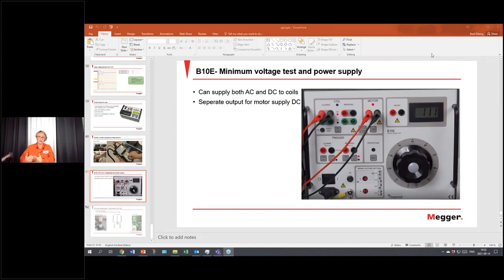It has to have no lack of gas, so the vacuum has to be intact. But somewhere between 1 and 5 years, depending on how important your breakers are.